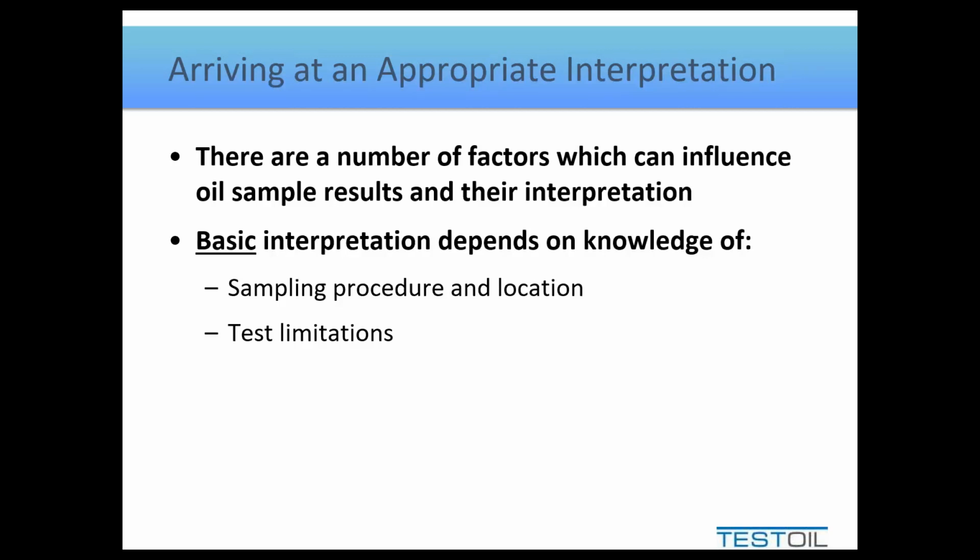But funnily enough, if you're good at interpreting reports, you may know that the lack of correlation can be just as telling. And what I mean by this is if you have a high wear metal count but a low particle count, it means all the particles are small and therefore probably caused by normal wear modes. If both tests are high, they correlate the way you might expect, it indicates you have both small and larger size particles, which means it's transitioning from normal to abnormal. But if your wear metal count is low and your particle count is high, it means you've got nothing but large particles. And that could mean greater severity to the problem.